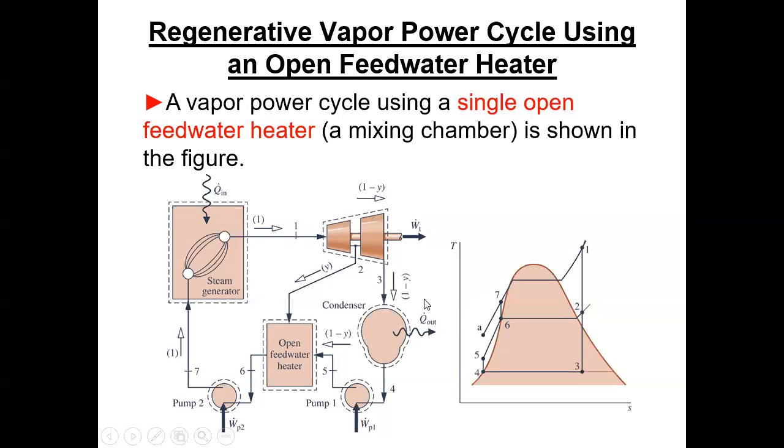And my condenser, does it see the full main steam flow? Well, no, it sees 80%. Okay, 80% through the first feedwater pump, 80% in here. But then guess what? In this cycle, I put in 80% here, I put in 20% here. Now I've got 1, or 100%, of my flow coming out of the open heater. So pump 2 sees 100% of the main steam mass flow. Pump 1 only sees 80% of it. And you have to keep track of this all around the cycle.